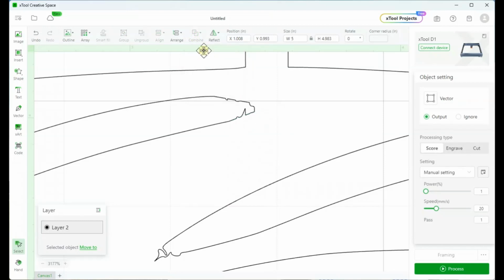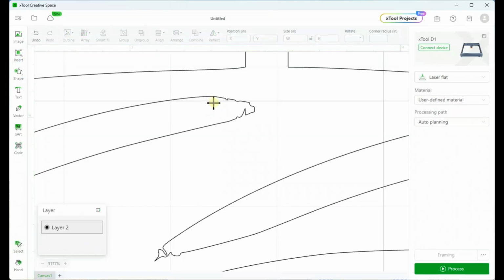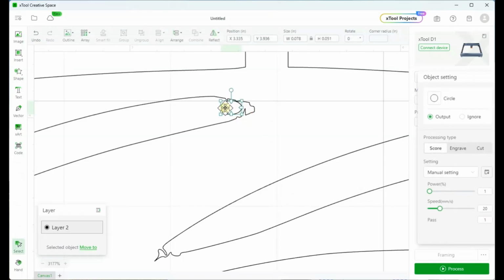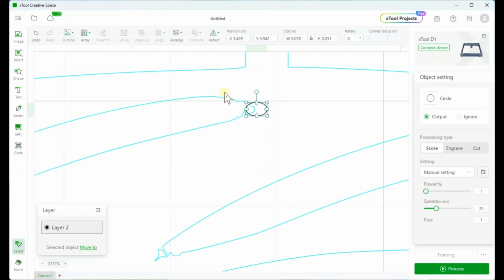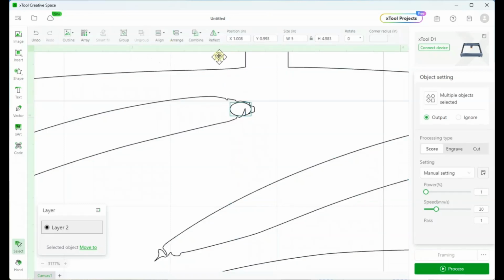So if I'm wanting to take away, like I'm going to do right here, I'm going to draw a circle inside of this to round out this area. And see, I've got that little piece that's poking up into what is being cut out. So I'm going to use this and subtract from this area inside, and then the software will remove that little projection. So you can see right here, hit subtract, and now that's smoothing that out.